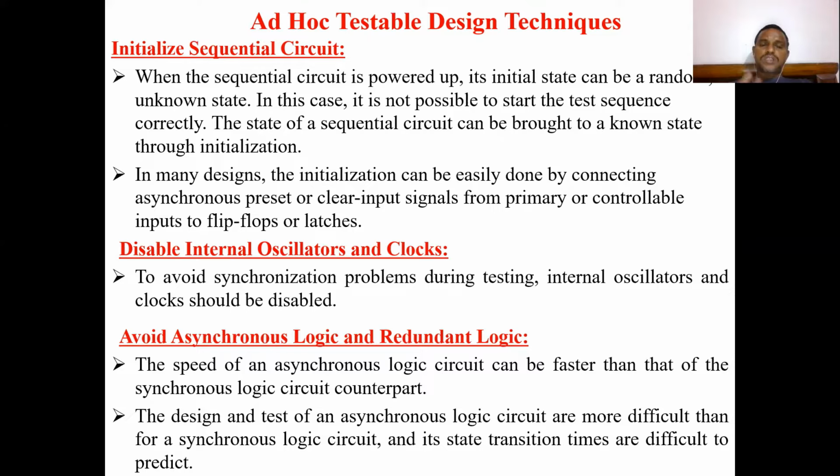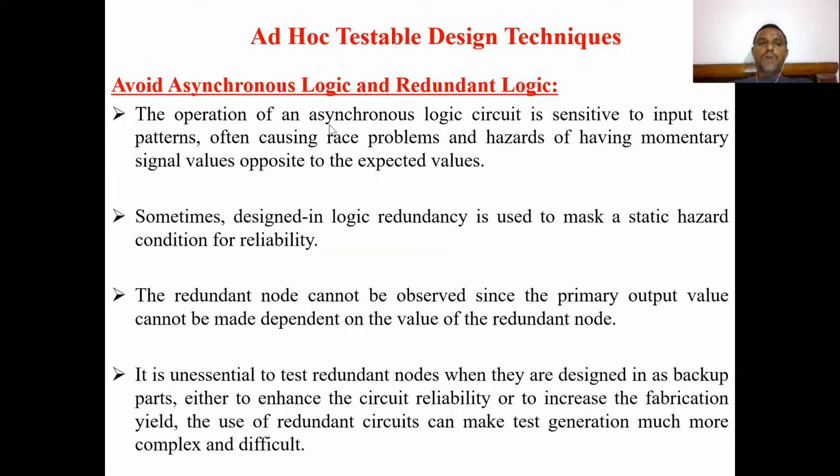If we want to test an asynchronous logic circuit, we cannot predict its transition times due to its speed of operation. The design and test of an asynchronous logic circuit are more difficult than for a synchronous logic circuit, and its state transition times are difficult to predict. The only reason is that asynchronous circuits are very speedy. The operation of an asynchronous logic circuit is sensitive to the input test patterns, often causing race problems and hazards of having momentary signal values opposite to the expected values.